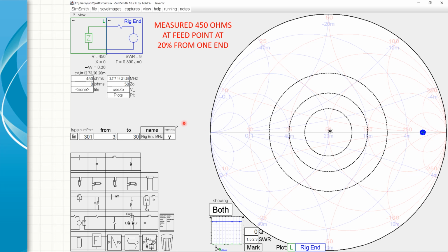I'll just make a note here that if you store what's called an S1P or an S2P file, which is the reflected signal off port 0 of your NanoVNA that's used for SWR, or the port 1 channel for through readings of things like filters and other devices, where you're measuring the performance through the device as opposed to reflected from the device, you can literally import that to your PC and drag and drop it right here, and it'll replicate that antenna in SimSmith.